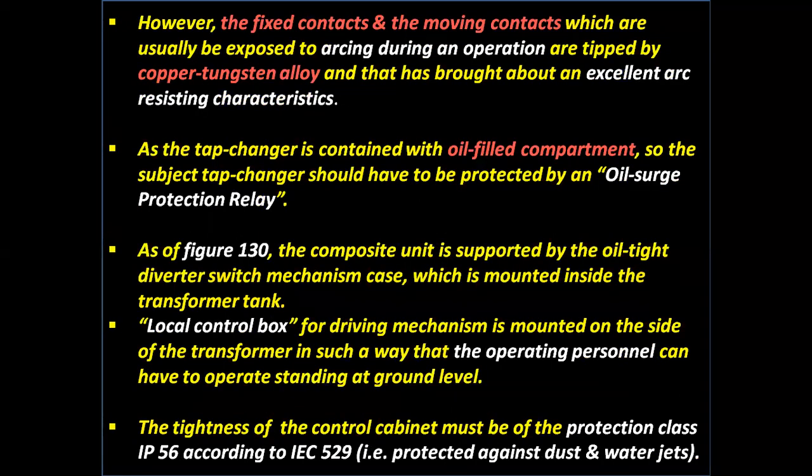However, the fixed contacts and the moving contacts, which are usually exposed to arcing during an operation, are tipped by copper tungsten alloy, and that gives excellent arc resisting characteristics. As the tap changer is contained in an oil filled compartment, the tap changer should be protected by an oil surge protection relay.